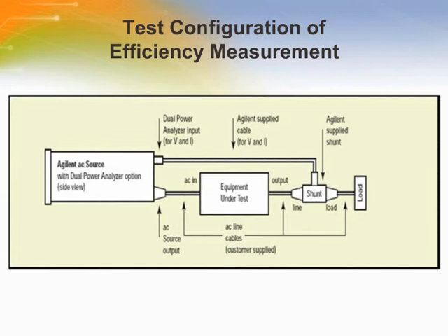The 6800 series can help you test and improve your products. It helps in measuring current harmonic content and creating custom AC power waveforms, such as the combined AC plus DC signal to stimulate a telephone ring, or measuring current harmonics, voltage fluctuations and flicker emissions, and generating voltage and frequency disturbances and interharmonics to determine product immunity.